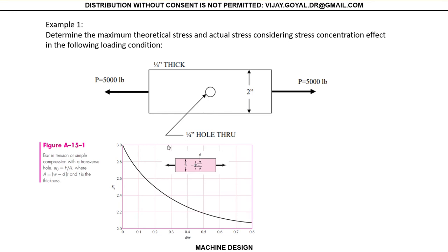Now, what you should know is that when you're talking about the actual stress, you're talking about the stress after you multiply by your stress concentration factor. Okay, in this case, I only have a purely axial load.